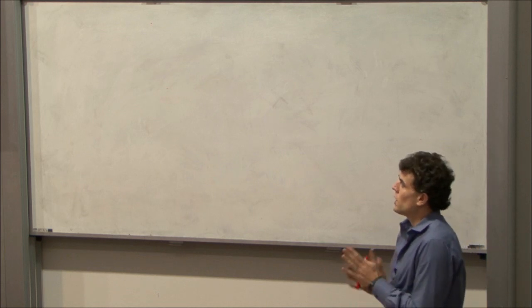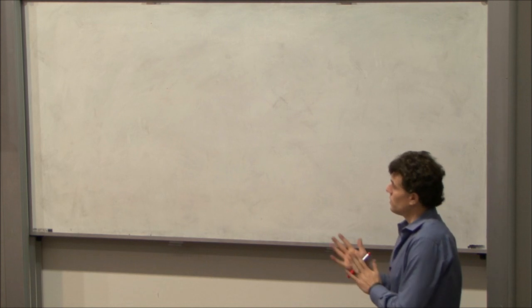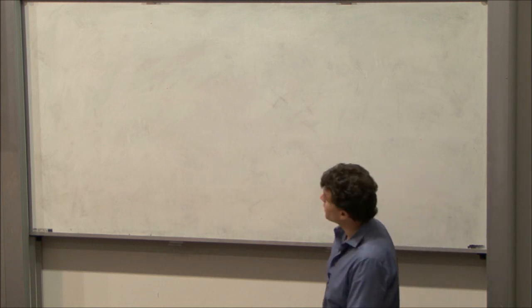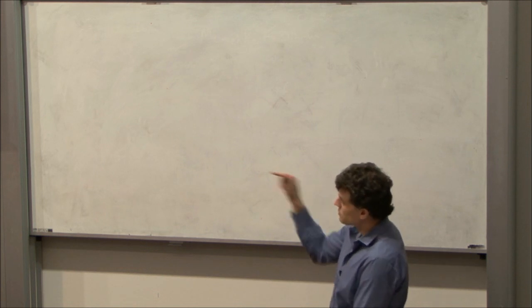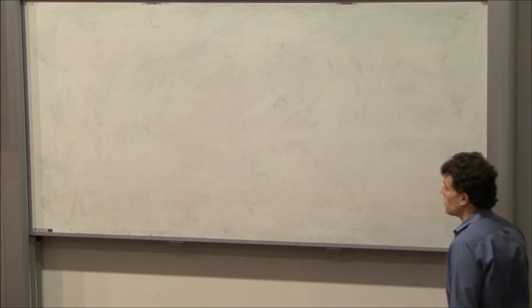Now this method relies on the assumptions we said on the previous slide, that our skin can't take transverse loads or point loads, and that stiffening members only take loads in the direction that they are carrying them in.